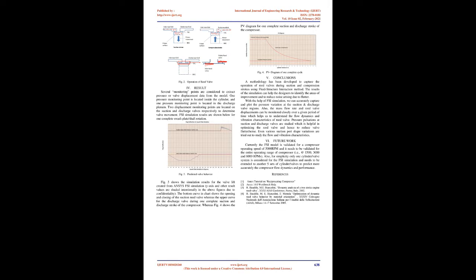Problem setup. The domain includes part of inlet manifold, cylinder, piston, inlet/outlet valve and cylinder head, which accommodates both inlet and outlet valve seat, schematically shown in Fig 2. In this simulation, piston is positioned close to the TDC to start with. Mesh is generated using hexahedral and prism elements in the CFD model. There are two dynamic mesh zones in the CFD model. The first zone is to capture the motion of the inlet valve and the second zone to capture the movement of the piston, which is done using the layering option of FLUENT.